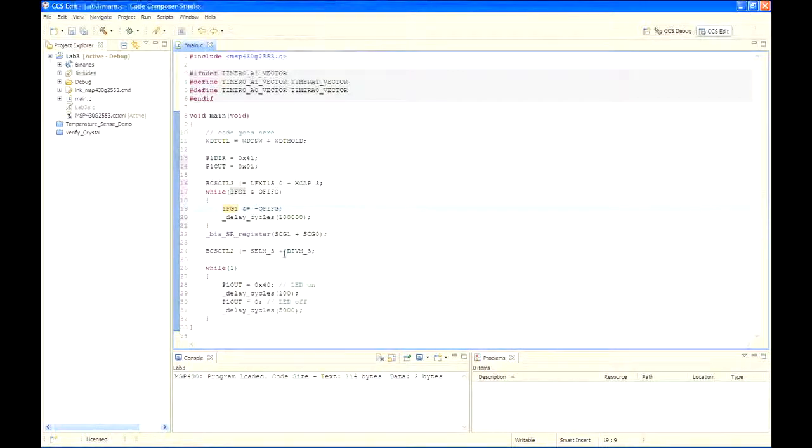That while loop tests the flag in the register. If that fault flag is clear, then we exit the loop. We need to wait about 50 microseconds after clearing the flag before testing it again. That delay cycles is a lot longer than that. We need it to be that long so that we'll be able to see the red LED flash at the beginning of the code. That way we know it's been tested. Otherwise, it would flash so quickly that our eyes wouldn't be able to see it at all.